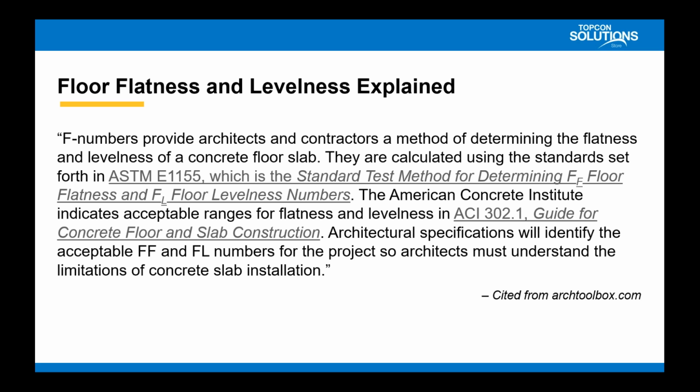The American Concrete Institute indicates acceptable ranges for flatness and levelness in their guide for concrete floor and slab construction. The part that I really wanted to look at here is this last portion. Architectural specifications will identify the acceptable FF and FL numbers for the project. So architects must understand the limitations of concrete slab installation.